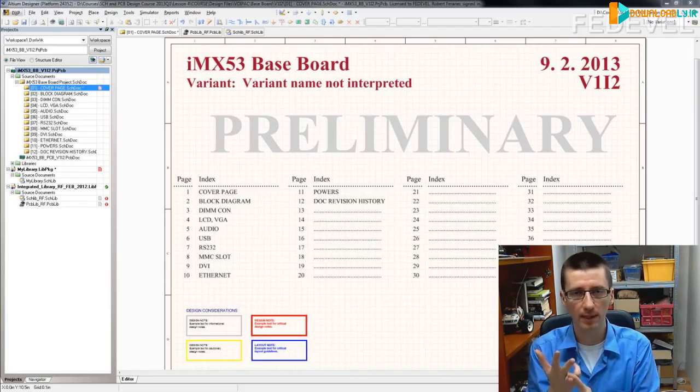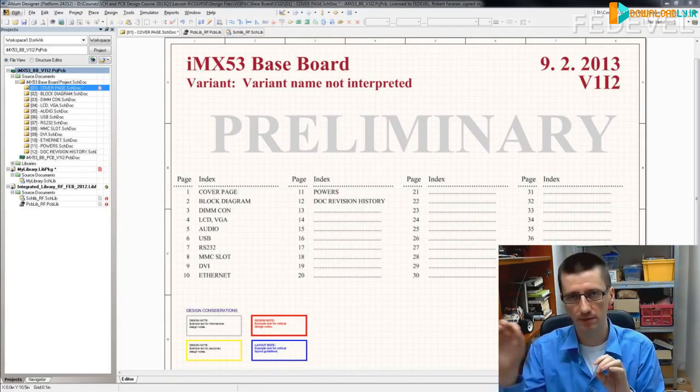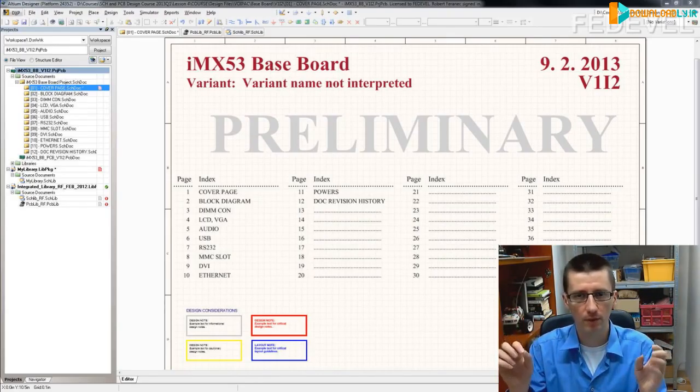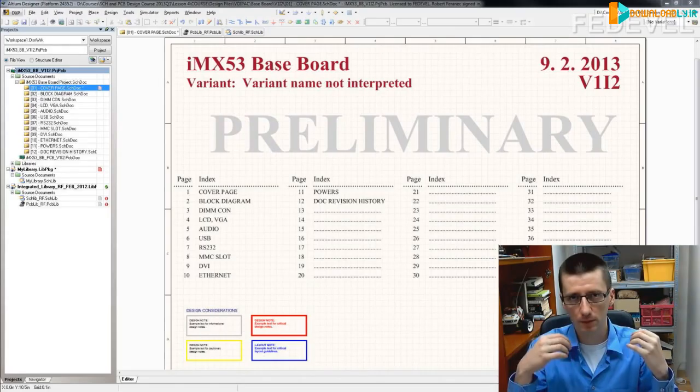You also replaced all the schematic symbols with the symbols from your library, and that's why the schematic is in a preliminary stage. What you need to do now is see if everything actually fits on your board, because the board shape is many times defined by the enclosure, by the system where the board is mounted, or by a specification, form factor, or I don't know, anything else. So your components may not fit on the board.